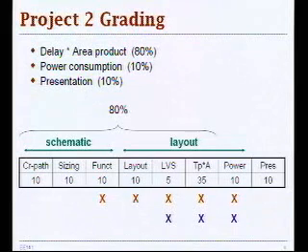Now, if you go through the functionality check and you successfully do the layout and you fail LVS, then that's an indication that maybe something is wrong with your layout, that you are trying to squeeze in too much area, and then you have to report your propagation delay times area. And again, if you didn't pass your LVS, that means your extracted circuit may have some malfunctionality.